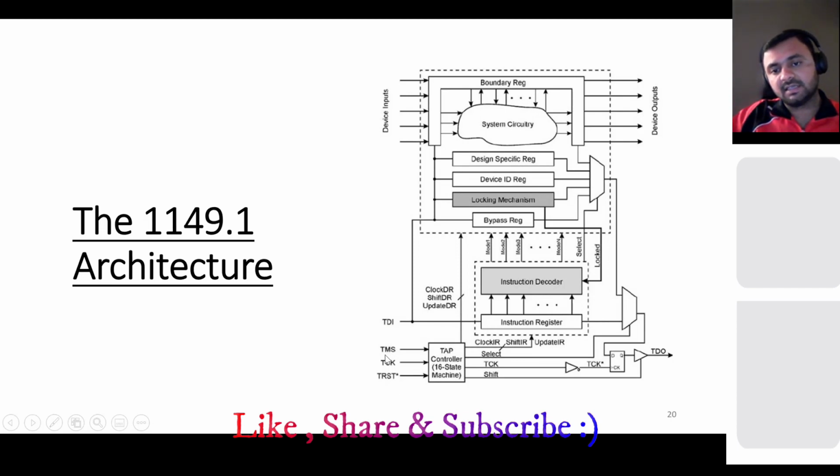This signal will go to the TAP, the 16-state machine, and this will generate some internal signals like clock IR, meaning instruction register, or DR, data register, and then generate some shift signals and all. Based on that, it will select a particular instruction register, then decode that instruction, and then it goes to your system circuitry.